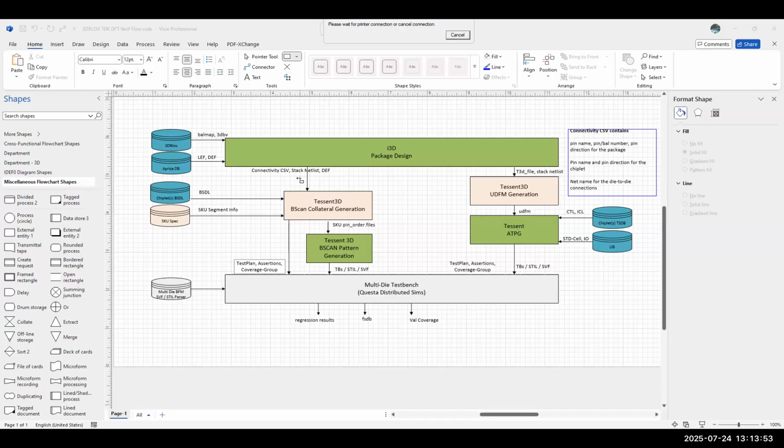Okay. So now when you have multiple chips in a package, it's a different problem, right? Because if you have 5 different chips, your primary IO is hooked up to a bunch of different chips, right? Right. And there are tools and workflows that will effectively, once you put this whole thing in a package, create a BSDL, so at the board level you can test the IO to your SIP. Let's call it a SIP instead of a chip, right?